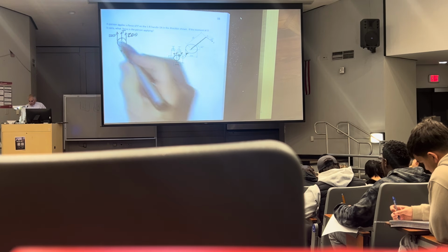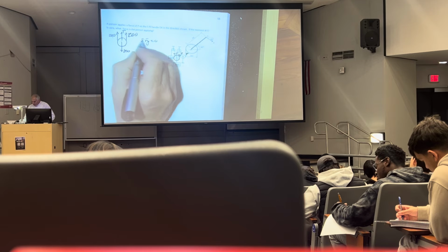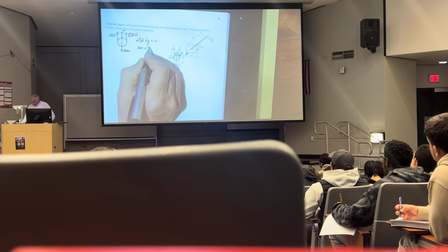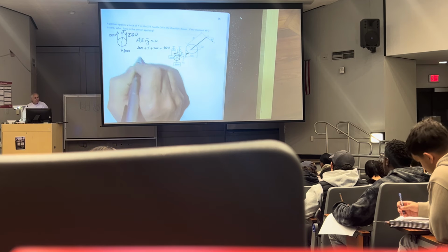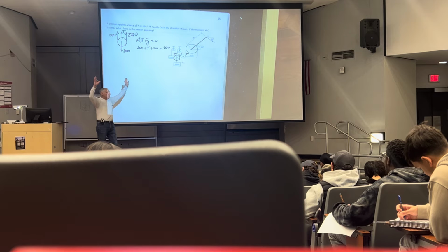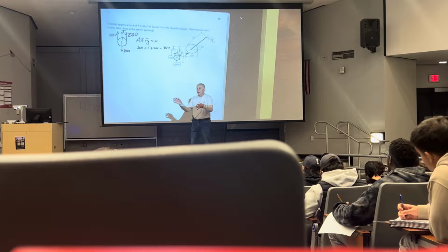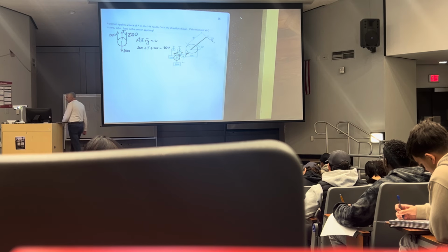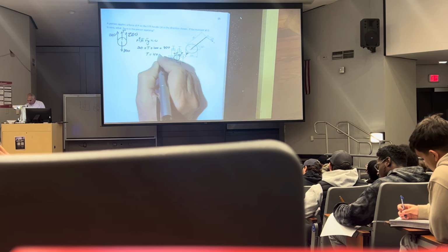Sum of forces in the Y equals 0, positive up. That's 200 plus T plus 200 is equal to 800. Another way of looking at it is to say, hey, the ups must equal the downs. That's really what you're saying. Or the lefts must equal the rights. That's equilibrium. If I solve this, you know what T is. It's 400 pounds.